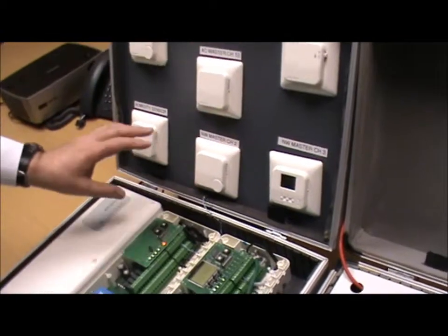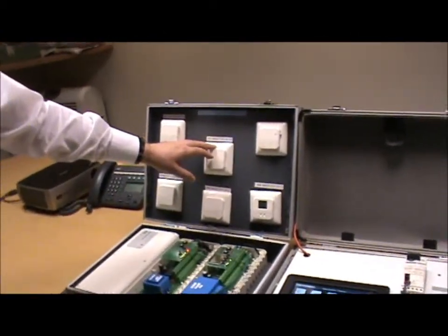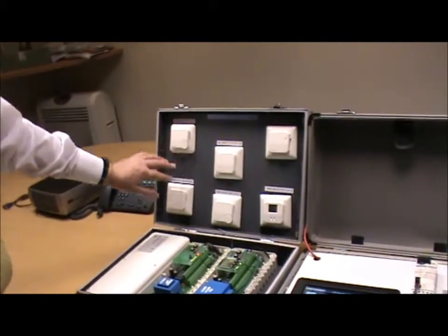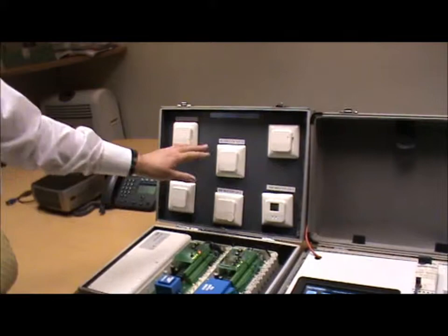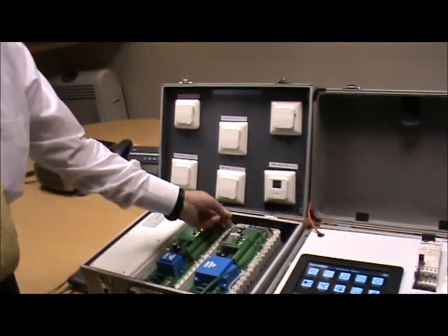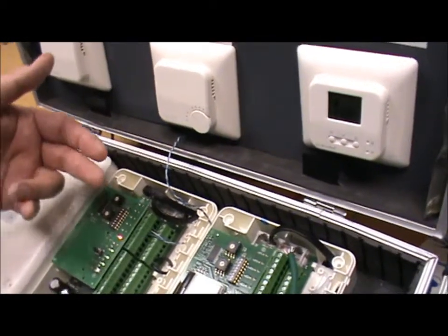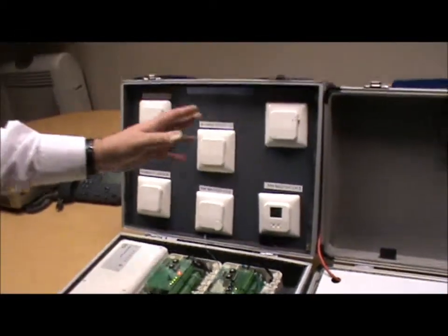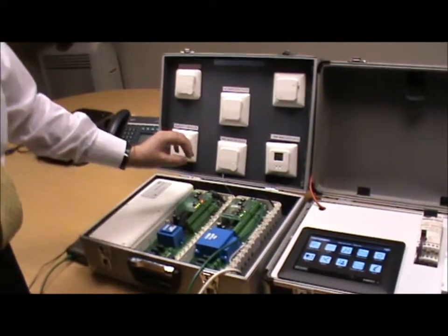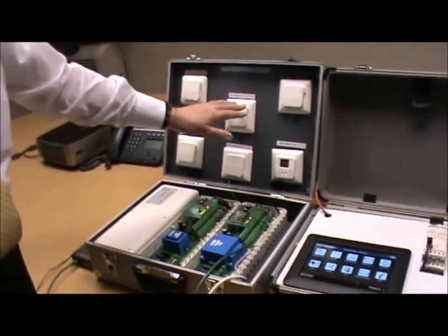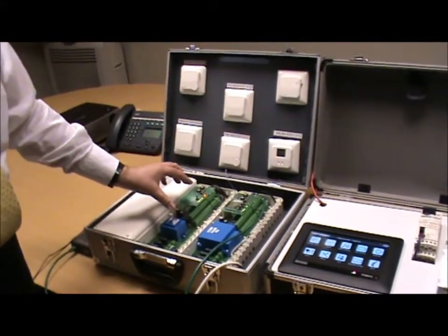What we then do is we have a range of sensors, which are intelligent sensors, which are individually addressable back to the master unit. The connection of these are used via a basic 2-wire Cat5. We daisy chain all of those together on one network back to the controller, and then effectively address each of those individually so that the intelligent sensors are picked up.